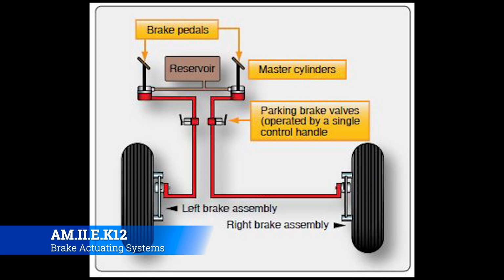The brake pedals move a long distance, which compresses the master cylinder, which then compresses the fluid inside the brake lines and pushes out on the slave cylinders, which we also know as the brake calipers or brake pistons, that push the brake lining or brake pads against a rotor that slows the wheel down from turning.